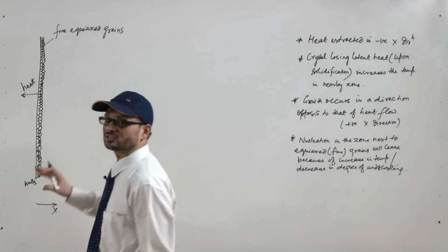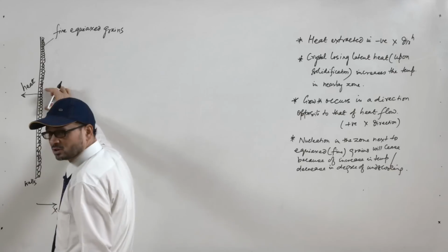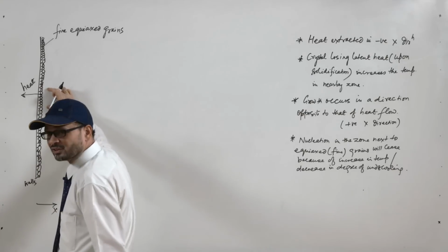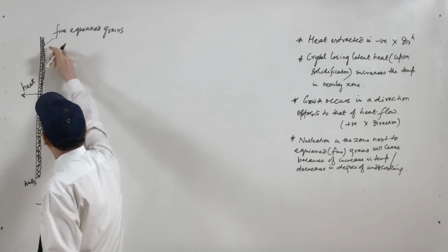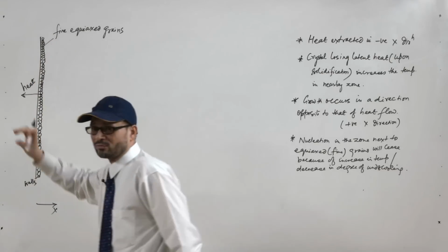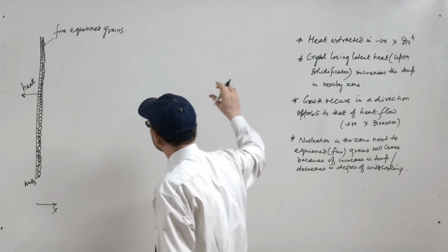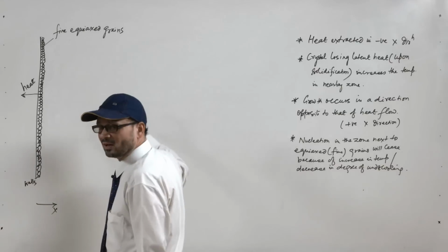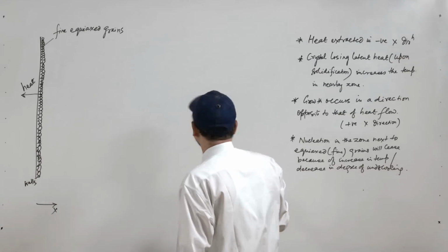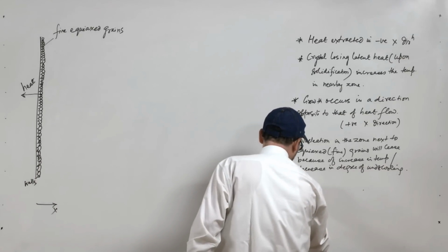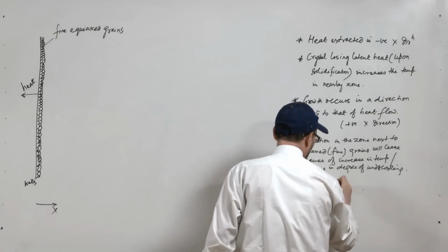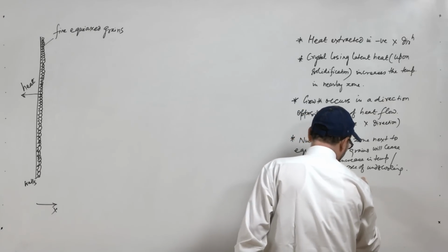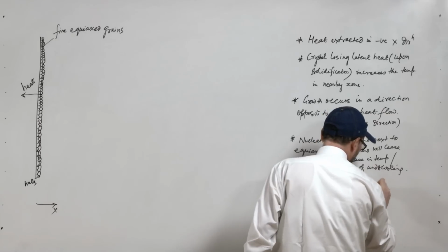Now, since growth becomes predominant here, there will be growth of these particular grains formed, in the direction towards the center of the casting. Growth is also in preferred crystallographic directions.